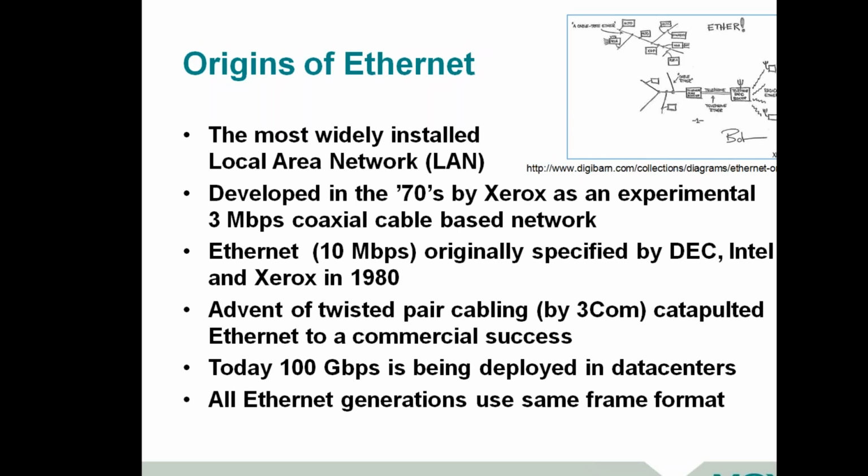Looking back, it's kind of funny that it was only 3 megabits as its first approach to the marketplace, and then it jumped to 10 megabits per second, with a real first commercial push. The thing that really catapulted it into popularity was the ability to move past the former coaxial cable type of connections and go to twisted pair, which most of you are familiar with today, whether it's Cat5 cable that you might use at your desktop or within a control panel.